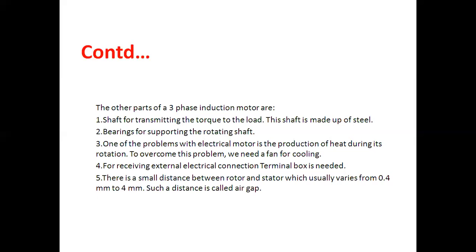To overcome this problem, we need a fan for cooling. For receiving external electrical connection, a terminal box is needed. There is a small distance between rotor and stator, generally varying from 0.4 millimeter to 4 millimeter. Such distance is called the air gap.